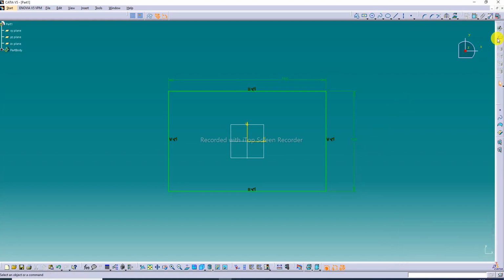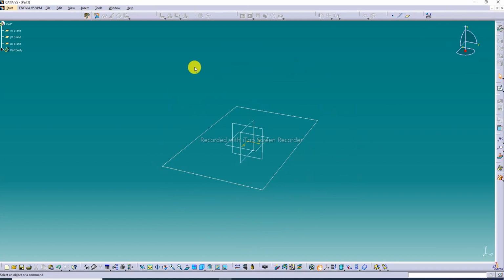Okay, this is a perfect sheet. Create here. At first, unless this command is clicked, the other commands are not active. At first click Sheet Metal Parameters, then all commands are active.